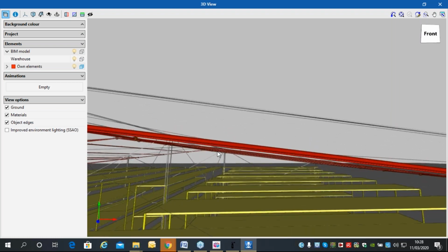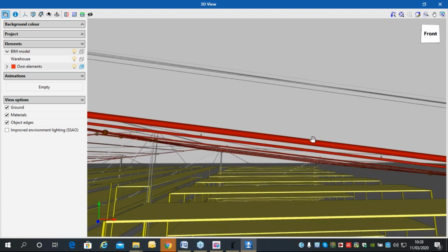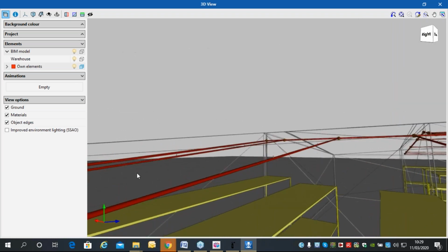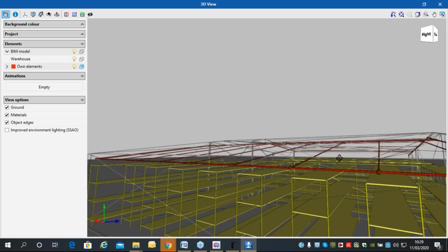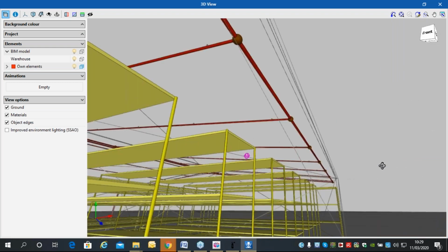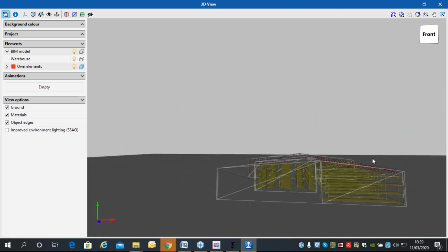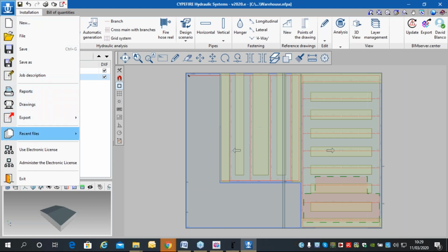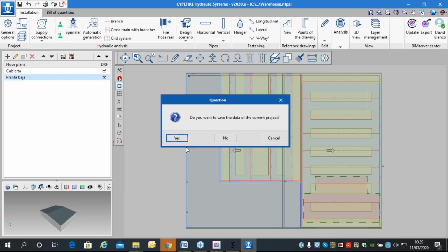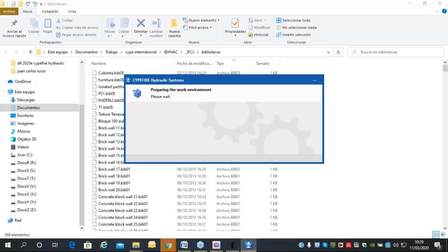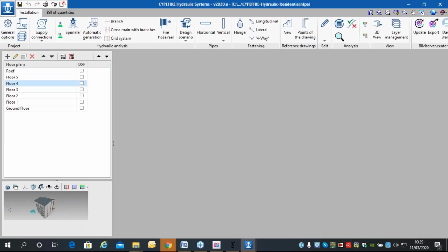All the sprinklers here, as you can see, are included, upright or pendant, in this sloped piece of pipe, taking into consideration the slopes of the roof of the building. This is also important, and you can always do it with the software. So in order to finish with this tool, I'm going to come back to the design I've made, and also I'm going to show you the bill of quantities.